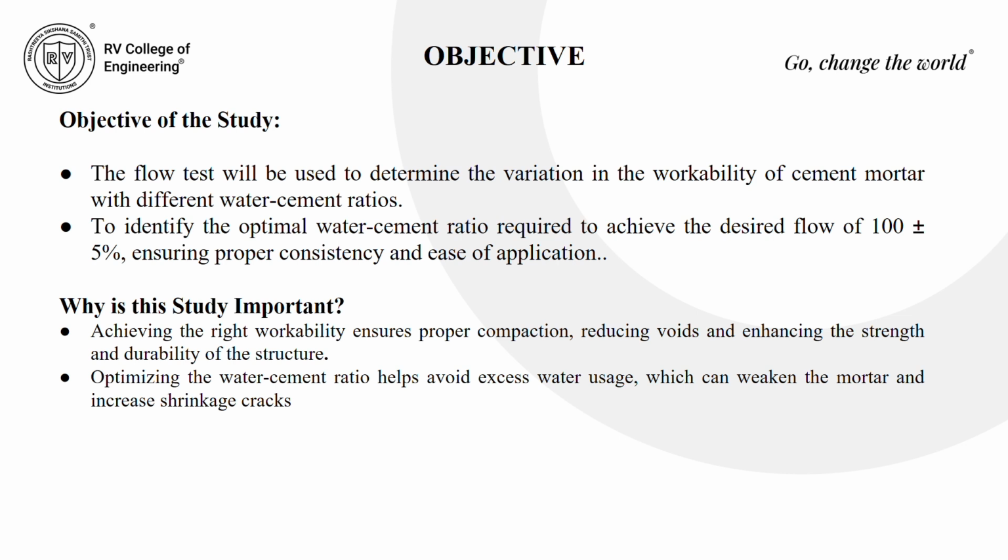The objective of the study is that the flow test will be used to determine the variation in the workability of cement mortar with different water and cement ratios, to identify the optimal water and cement ratio required to achieve 100 plus or minus 5 percentage.